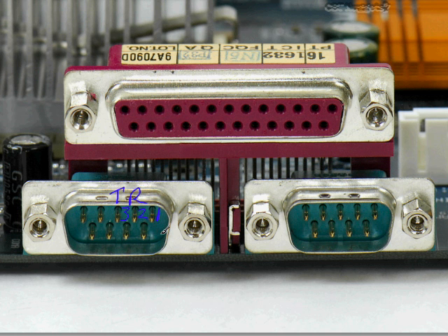And in terms of the null modem idea, what we would have here is we would send this through to another serial port, and I'm not even going to attempt to make a D shape down here, but this would be another serial port on maybe a laptop. Maybe I've hooked my laptop up to this PC because I want to diagnose some issues that take place during the boot process. Well, with a null modem cable, I could send out of the transmit on this computer, but when it reaches pin 3 on the opposite end, that's also transmit down here. That would be a conflict. We would have two pins that were set to transmit, and I would never be able to receive the data.